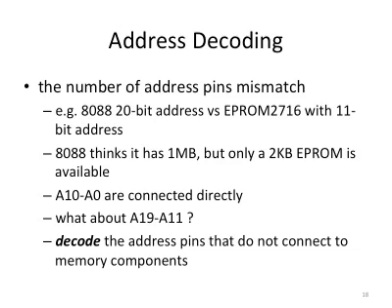So for this case, we know all of these 20-bit addresses from the microprocessor. That is to say, we have address bits from A0 through A19. We can certainly connect the lower 11 bits directly to the chip. So 20 minus 11, what about the upper 9 bits? What do you do with them?